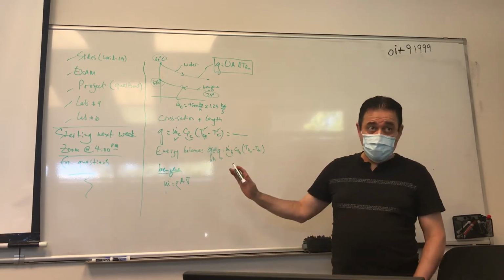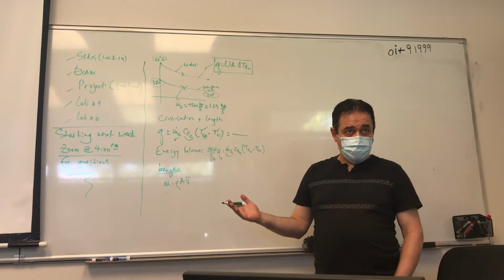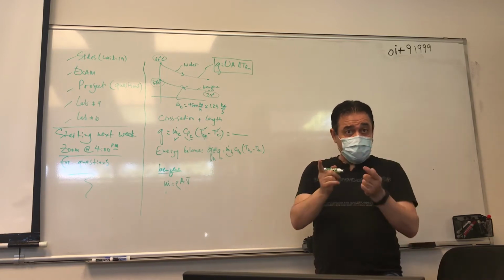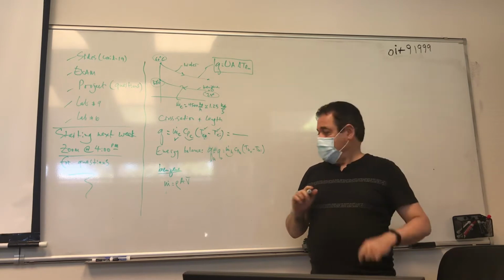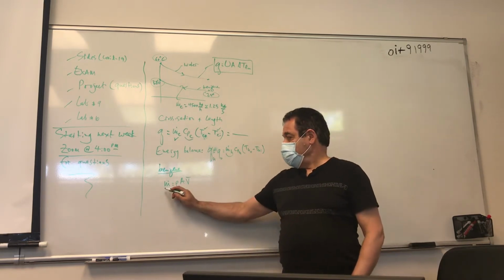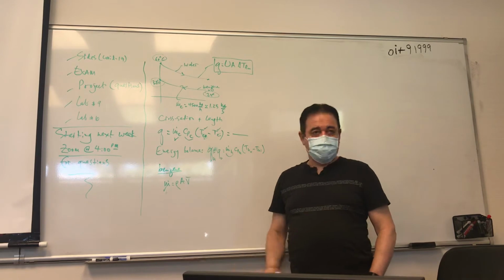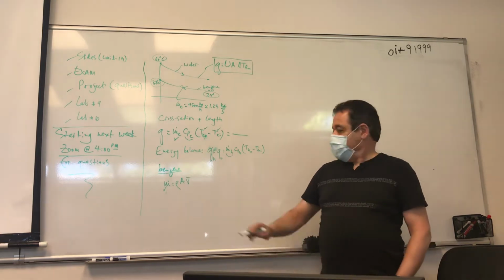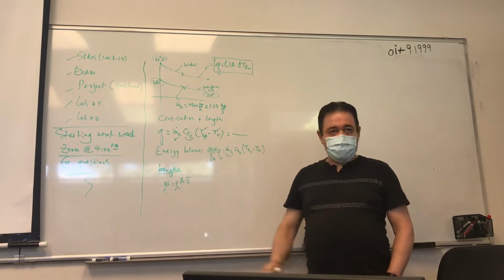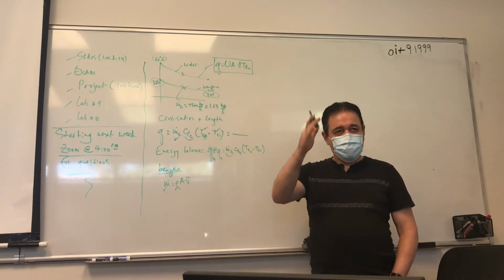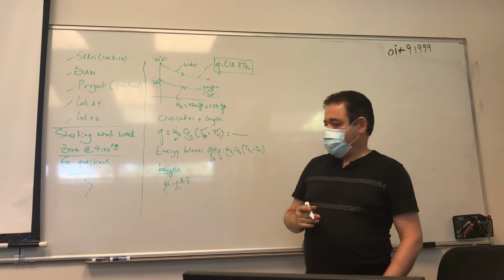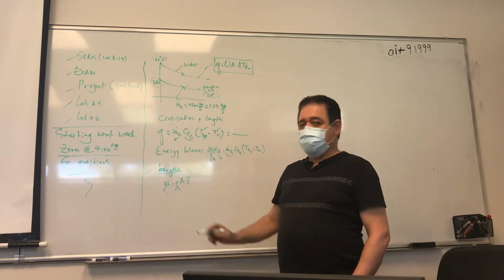This equation always holds for flow in pipes, whether you're talking about the annulus or the central part, right? Now, do we know the mass flow rate of the benzene? Yes. Do we know the density of the benzene? Yeah, you can interpolate, because you were given specific gravity in the table, right? And how about the velocity?